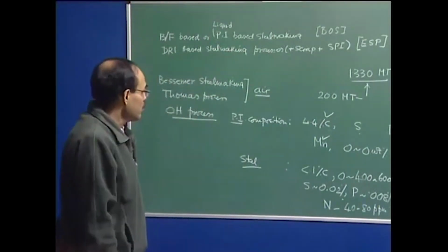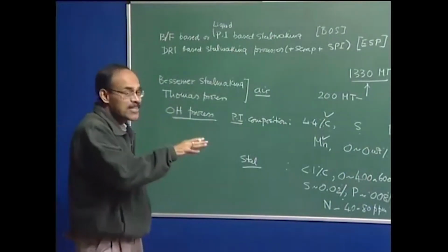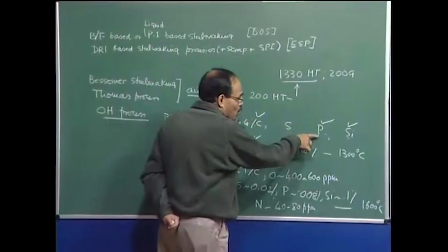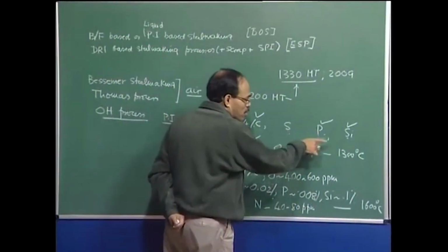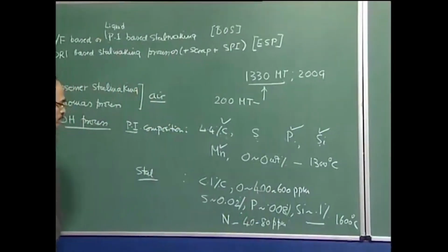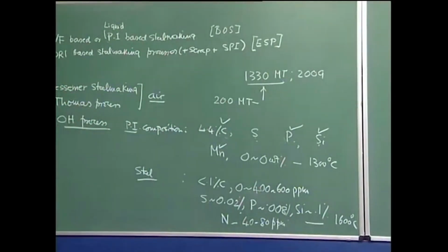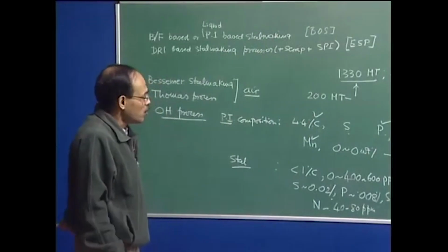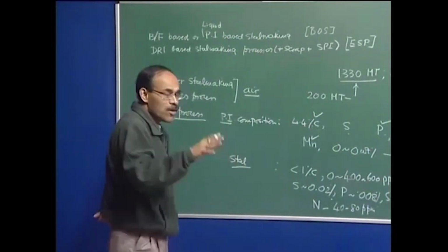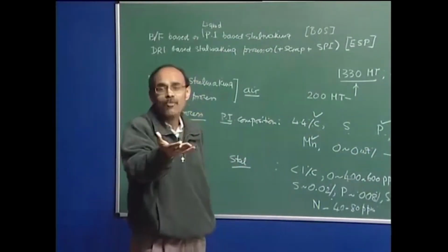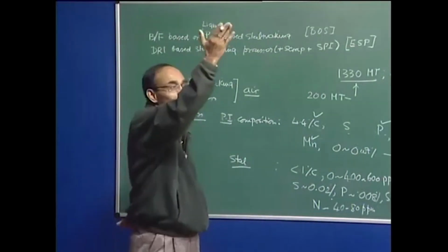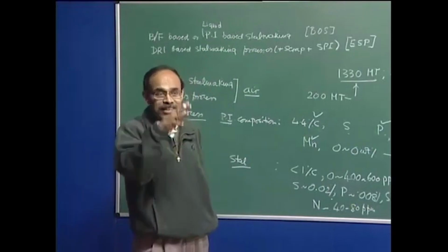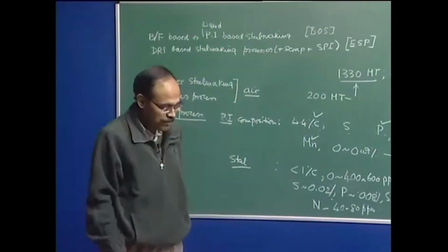In the case of the basic steel making process, it is used when the charge contains more phosphorus and less silicon, particularly in the basic Bessemer process. In basic steel making processes, you have slag basicity of more than 1, so you can afford to have the lining of the reactor also as basic. If you make the lining acidic, then the slag is again going to eat it up.